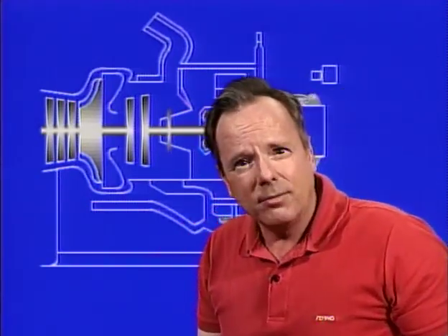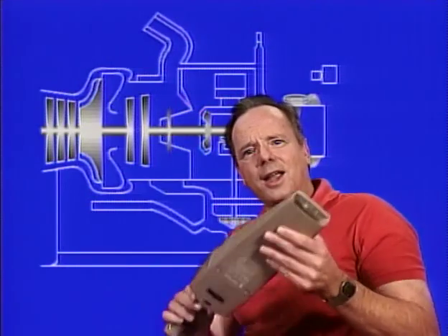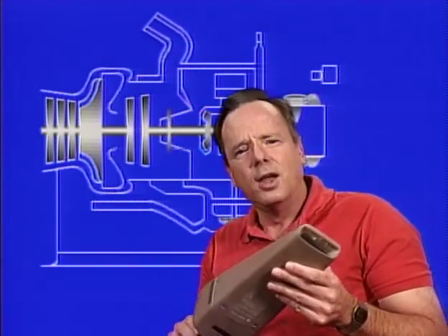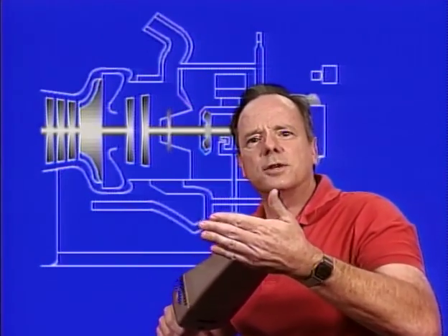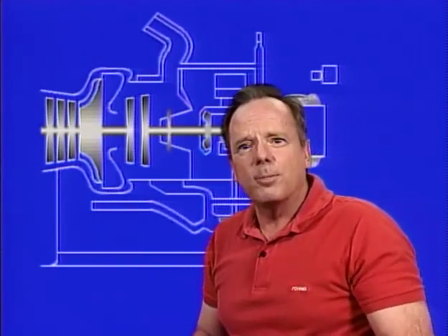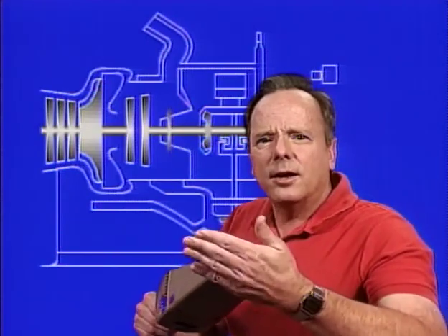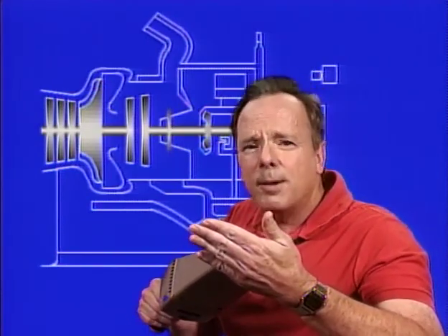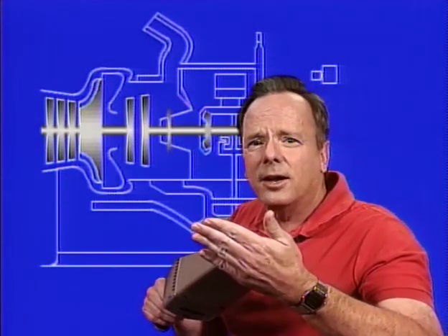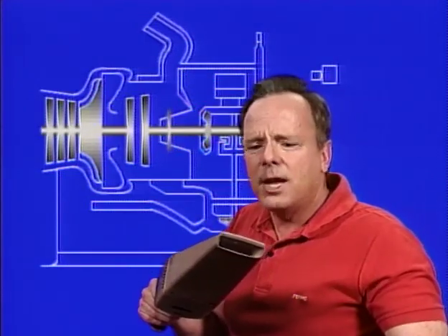You don't believe that? Let me prove it. I have here my handy-dandy dustbuster. I'm going to run this dustbuster, and I'm going to give less air to the dustbuster, and let's listen to see what happens to the RPM. Here is the normal RPM. It takes a while to build up here. Normal RPM, I block the inlet, and RPM increases. I open the inlet, RPM decreases.